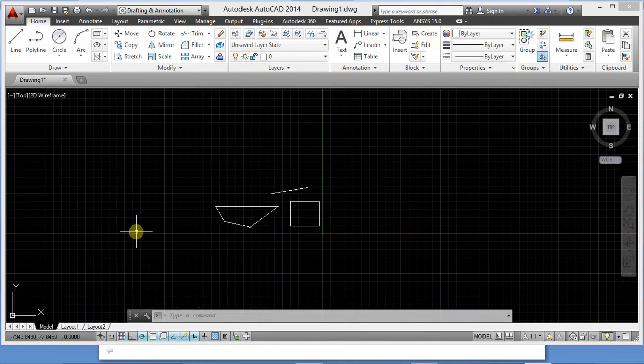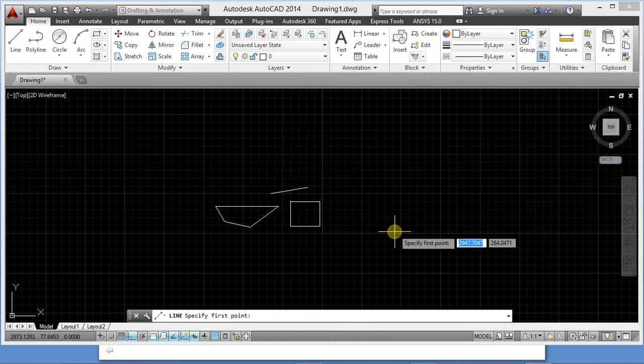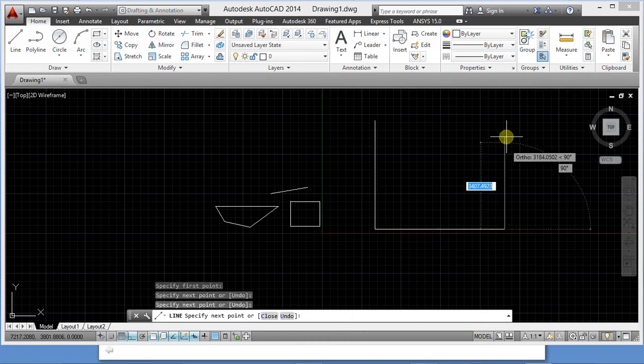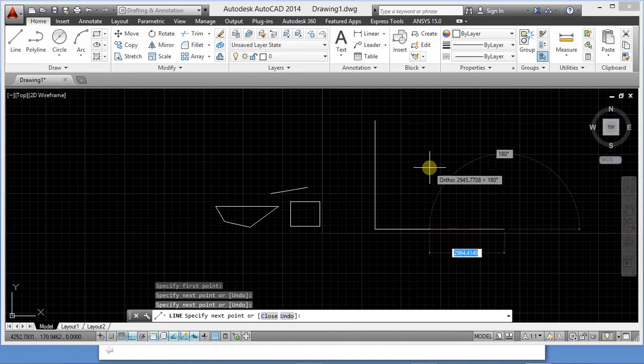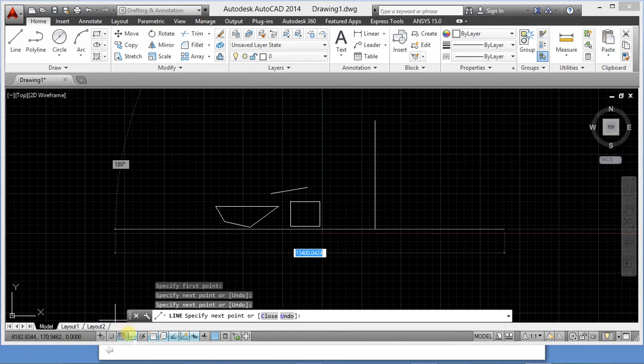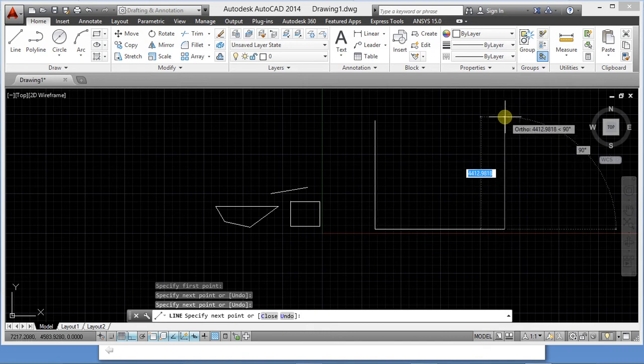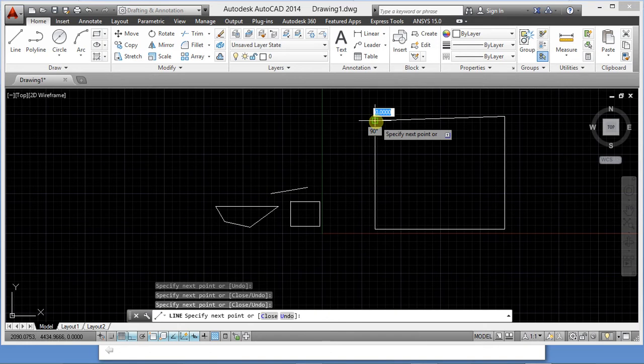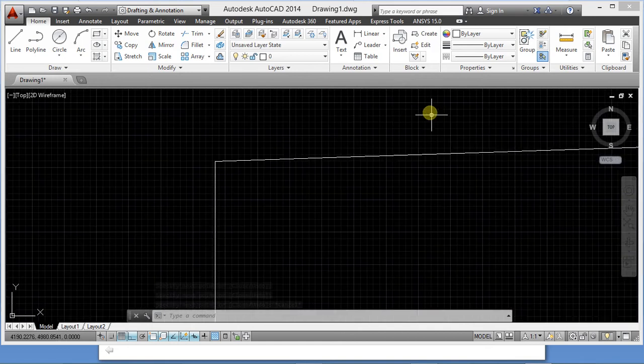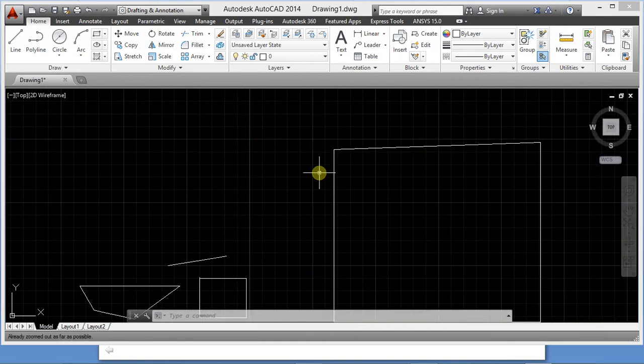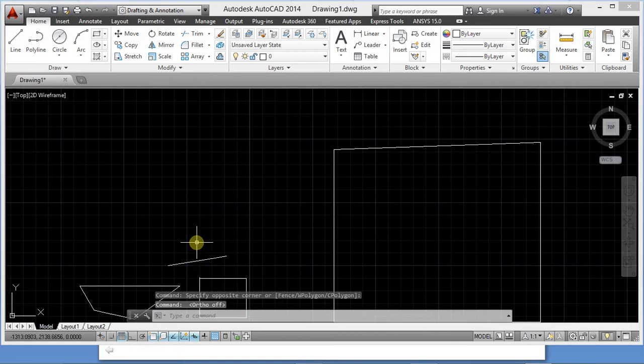Okay, so if the auto mode is on, it only gives you access to draw vertical and horizontal lines. If it is active, it doesn't give you access to draw a line at an angle. So with auto mode on, for vertical and horizontal lines only, if you want to put it at an angle, it will not give you a smooth line. So auto mode, F8, I deactivate it, press F8, it will not be active. So auto mode is for vertical and horizontal lines.